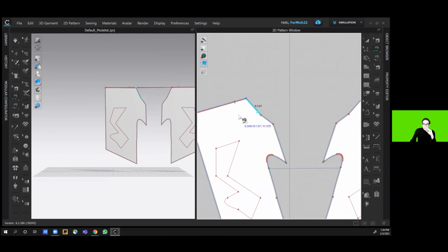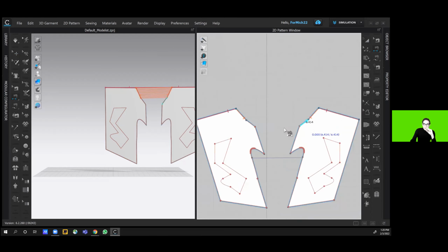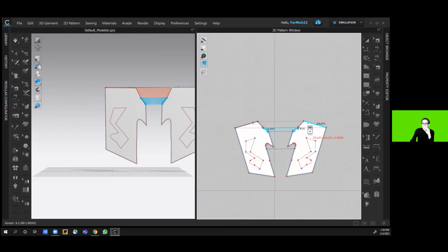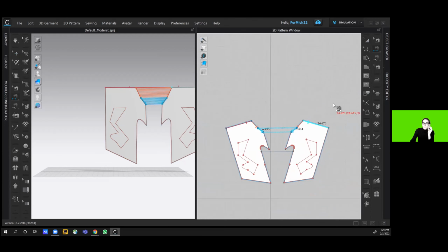So this is really useful for just sewing 2 things together. You can go along, etc. I did it backwards. But if you want to, let's say, sew a line segment of 2 different lengths or have more control over the extents of your seam, what you'll use is the free sewing tool. With the free sewing tool, you'll click and then drag the line to the length that you want to sew it. You'll start it again at the associated point and click and drag it a different length.